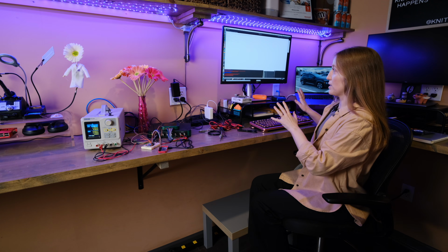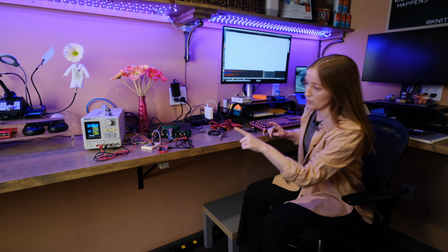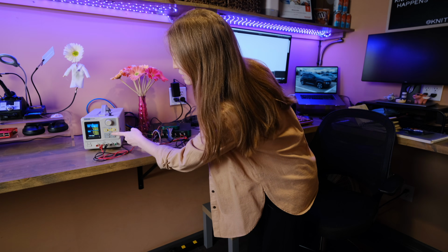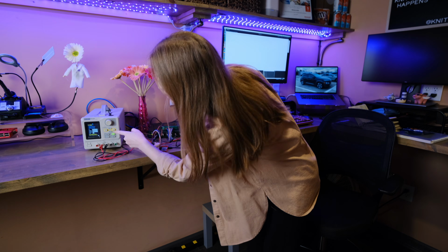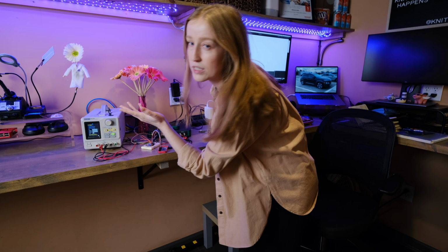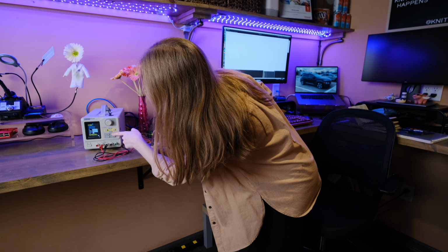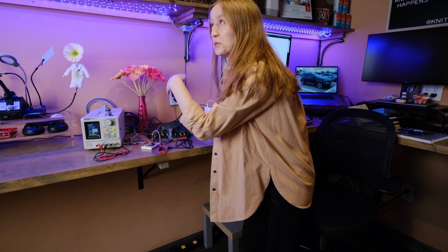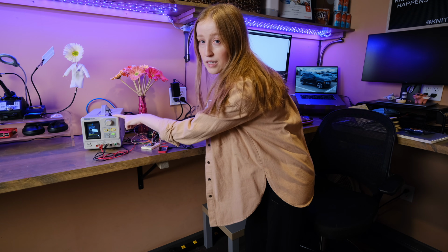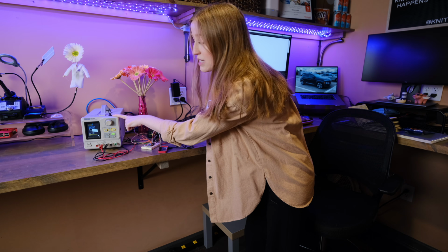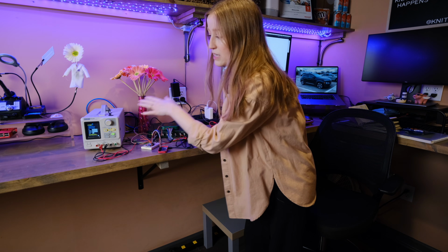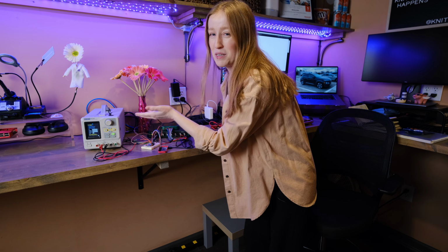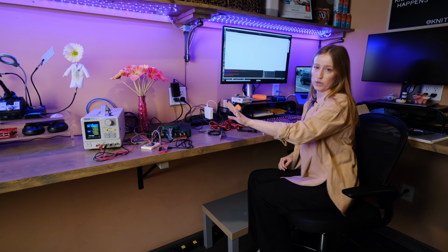So let's run this. Before I run it, let me double check. I've had trouble with this particular power supply changing IP addresses on me, even though I have DHCP turned off, which, okay. Of course, now that I said it would do it, it didn't do it. But, oh, I think I forgot to cover this as well. When you're setting up the bench before you leave it remotely, I highly recommend turning off DHCP. Otherwise, when you're on your remote PC, you'll have to query the local network of your remote setup every time to figure out what DHCP might have changed it to. So yes, always turn DHCP off.